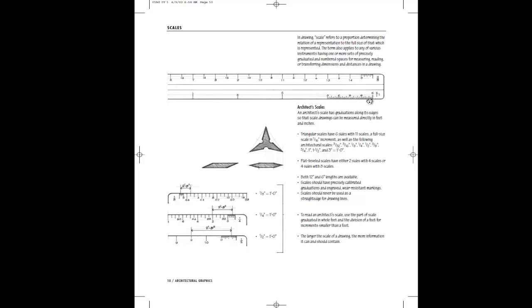There's 1 inch, 2 inches, 3 inches, and you can see in between these it's large enough so we can pick out 1/4 inches. So each of the little tiny segments on the line is 1/4 of an inch. So a distance from this line to here would be 1 foot 3 inches. Out here, even though that says 2, it's coming from the other end. This would be 2 feet 6 inches from here to here. So we can count these up and divide them.